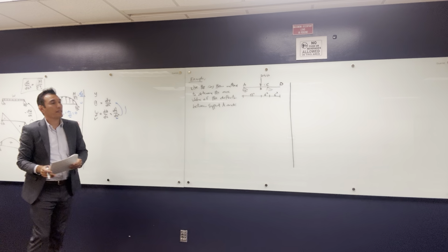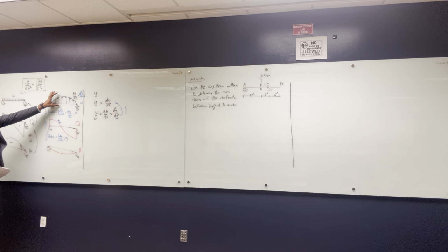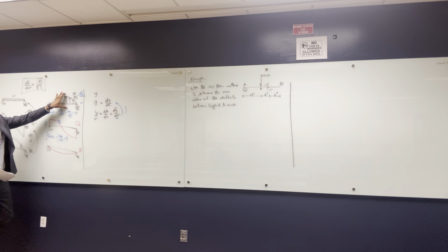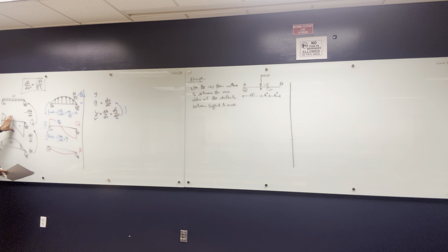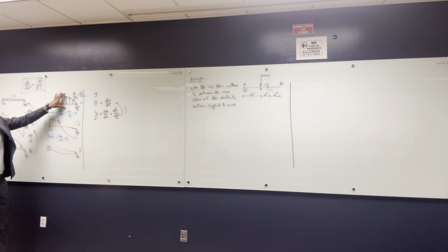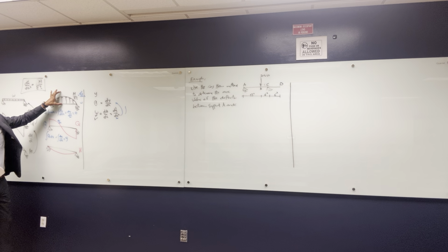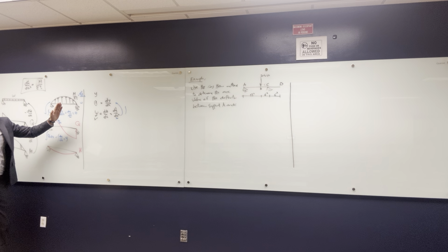So, if I give you an example like this in the exam or in the homework, all you have to do is draw the bending moment diagram, because I'm not interested in the shear. What I'm interested in is the moment, because this is the only value that I use so that I can divide it over EI. I'm not interested in the shear. So draw the bending moment diagram, step number 1. Divide the bending moment diagram over EI and deal with it as a load. And draw the shear force diagram and the moment diagram for this load, then you solve the problem.